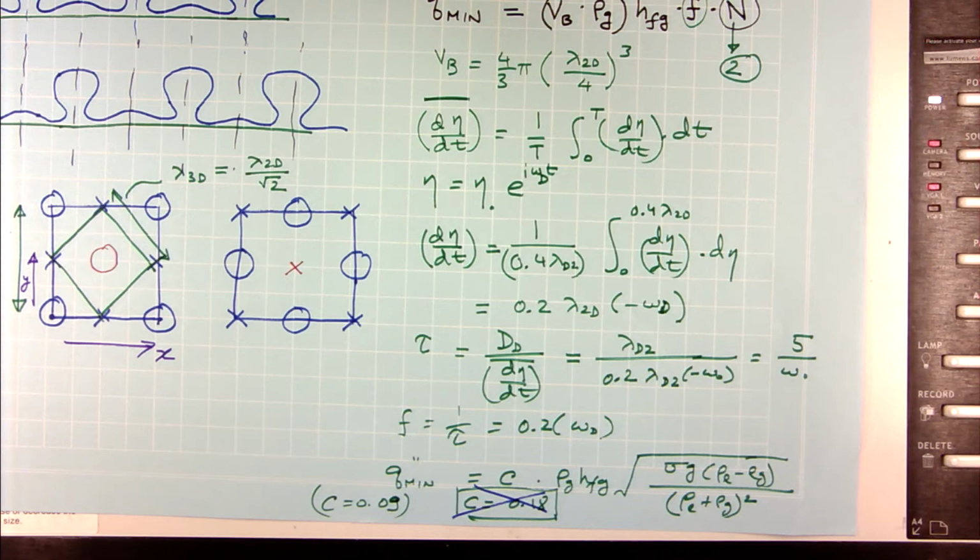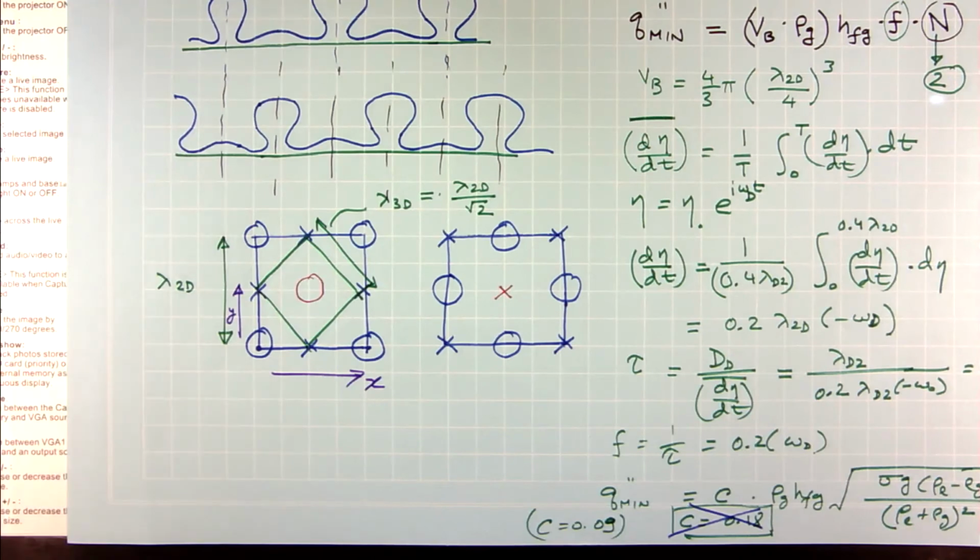Now, so far we have been doing the prediction based on linear stability analysis, but in reality a bubble will follow the linear growth rate only for a certain period of time. Okay, and then the amplitude of the disturbance becomes almost the same size as your wavelength, and so you cannot use linear stability analysis anymore.